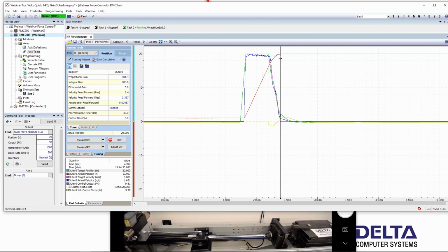Probably the biggest thing is a valve with either overlap spool or weak solenoids. You know, we like to have linear motor valves with powerful solenoids and good control. But if you do have a lousy valve that's not real linear, that can behave very similarly to what I'm seeing here. Valves that are non-linear with weak spools, they may have one thing on their spec sheet, but how they perform in real life can vary from that spec sheet more than what a high quality valve would.